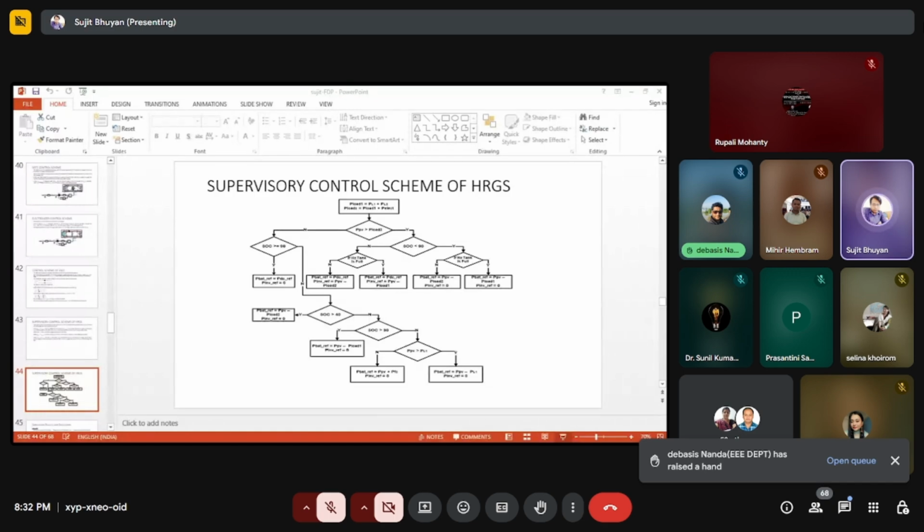Hello. Here the SOC comes into the phase. Why? Because the state of charge is less than 30%. And this is the voltage and current waveform of the hybrid renewable generation system. See here, the voltage and current waveform for the duration of 0 to 10, and I have taken a small portion between 7.9 and 8.1, and you can see the three-phase voltage, RYB or ABC. And this is the THD analysis, and you can see that the THD level is 0.17.